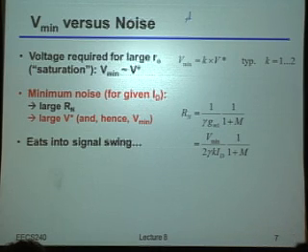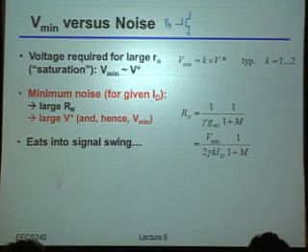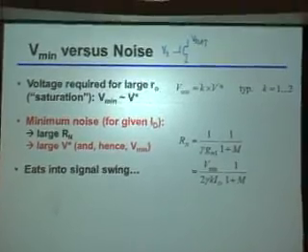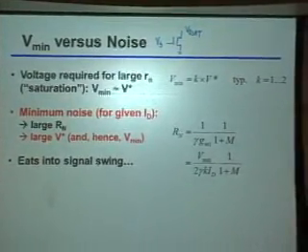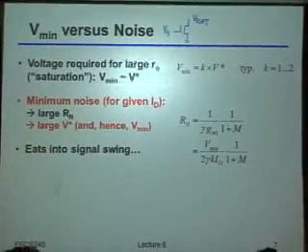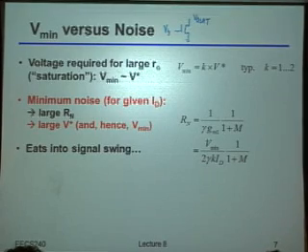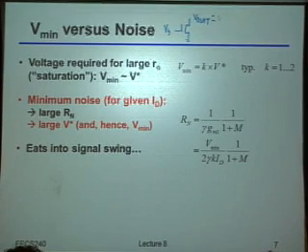Okay? So if we had a simple long channel device with some bias voltage, and we asked ourselves what voltage you needed across it to make sure the device was in saturation, meaning to make sure you had a sufficiently high output impedance? Well, for the classic long channel device, that VD sat would have just been V star, right? Now, remember, we're dealing with short channel devices, so V star doesn't really correspond to the saturation voltage.